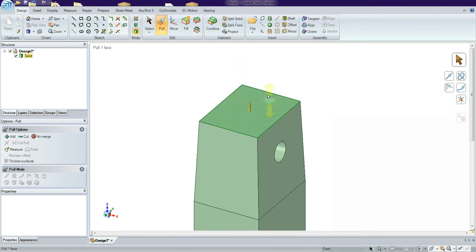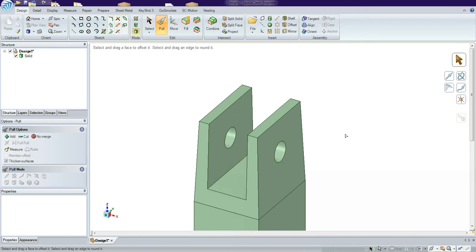Now I want to cut a slot in the top here. Traditionally I'd create a sketch, but all I'm going to do is reuse my geometry. So just choose this edge and choose this edge and say copy those edges again, and we'll pull them in 3mm, and then we'll pull down to create my slot. Very simple. I'm going to make it 20mm deep.